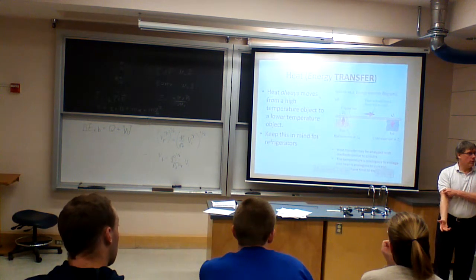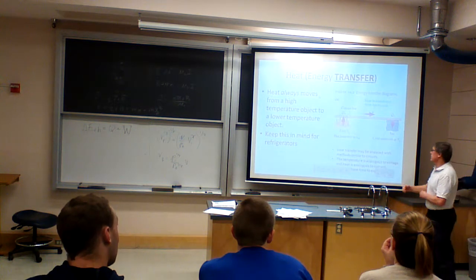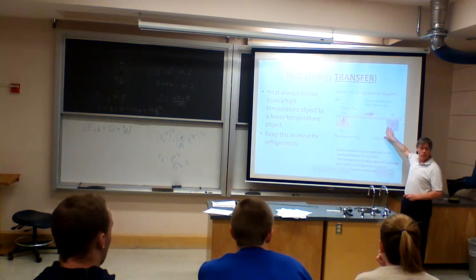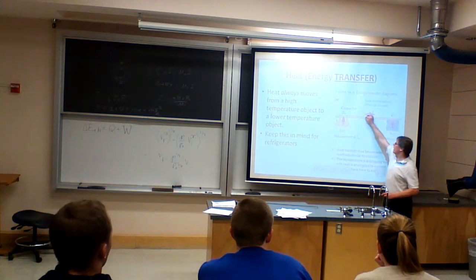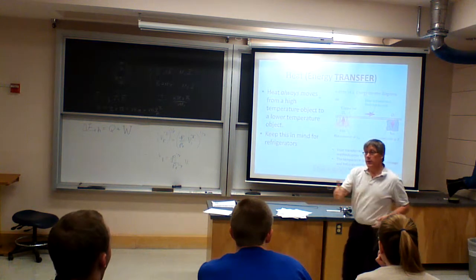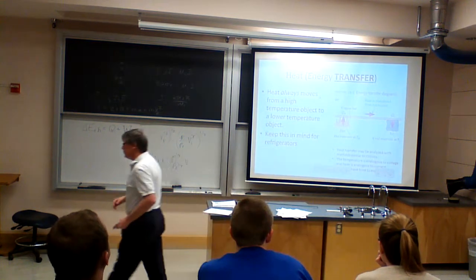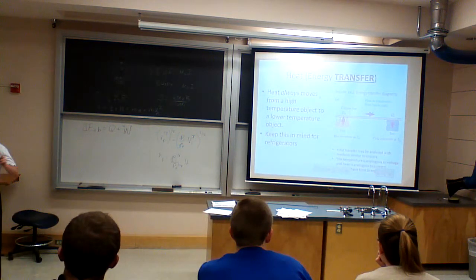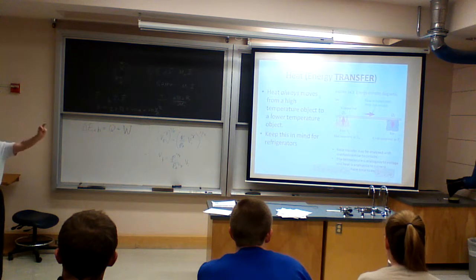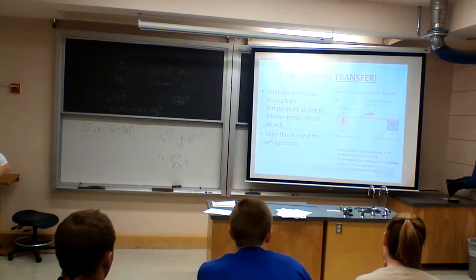When you model them in steady state, it's like a resistor. This temperature is like your positive voltage, this temperature is like a lower voltage, and you describe the material like resistance, and then you can figure out the heat flow. And not surprisingly, the bigger and wider the bar, the lower the thermal resistance; the thinner and longer the bar, the higher the thermal resistance.